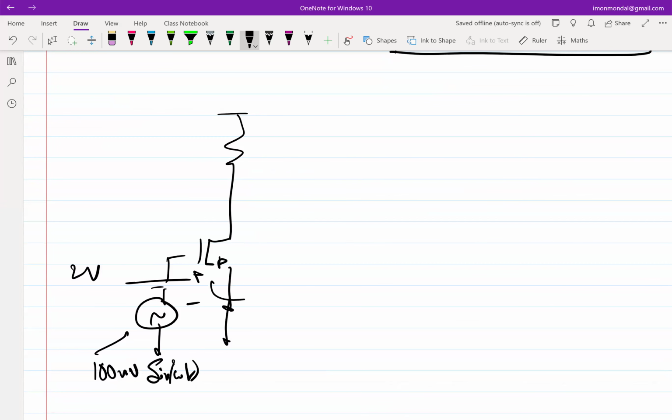So the VGS here is changing from 2.1 to 1.9. Even though VGS is changing by this much, we are still using the same old value of GM. And why was it being allowed? It was being allowed because for certain changes, we could neglect the higher order terms of the Taylor series. It essentially goes back to that old Taylor series neglecting thing. If we can neglect the higher order terms, we are good. We can use whatever approximation we can. If we cannot, then we cannot. Right? Okay.